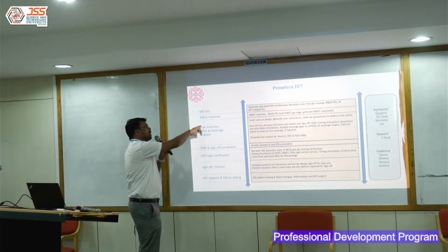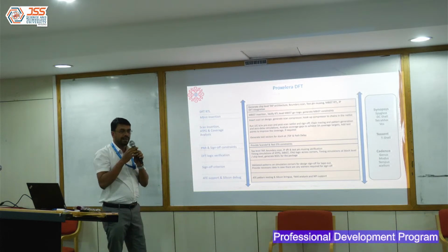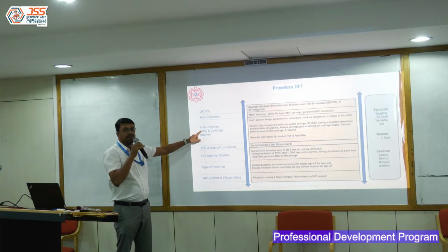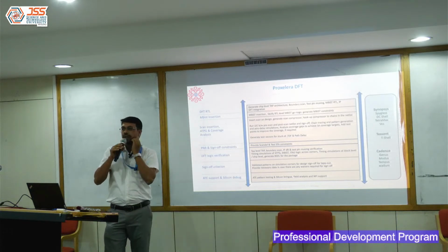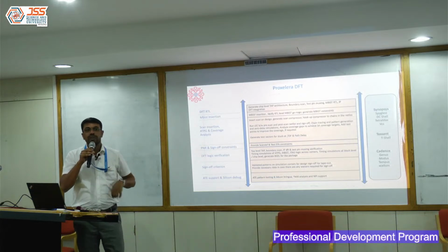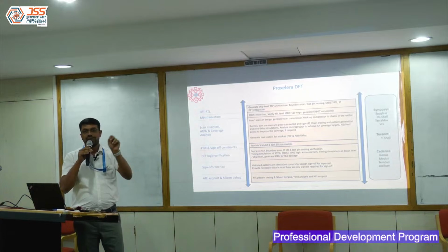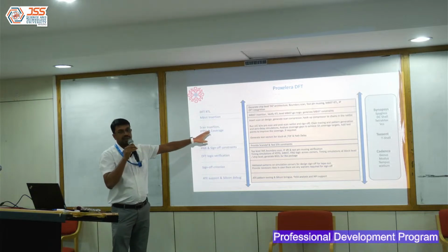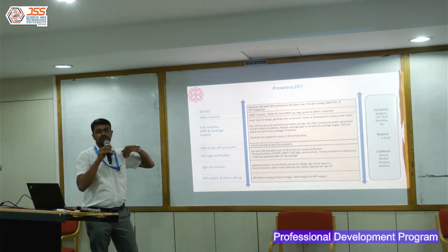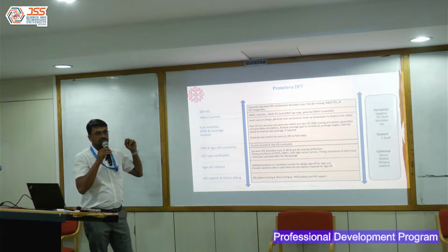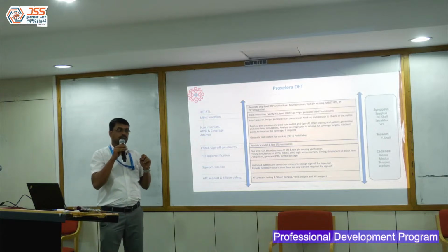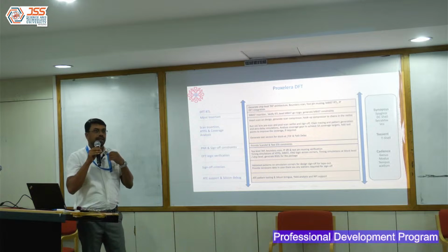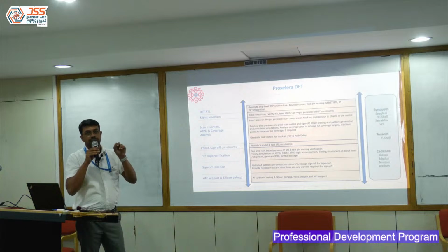And then it goes to synthesis. We get a netlist. Next comes scan insertion. So scan insertion is like, there will be the sequential elements, flip-flops. So we hook up all the flip-flops into a chain, like how we have a shift register. So that is basically scan insertion. So we form something called a scan chain. Now the scan chain is the one which is going to help us do the scan test. It is going to help us test all the internal points in the design.